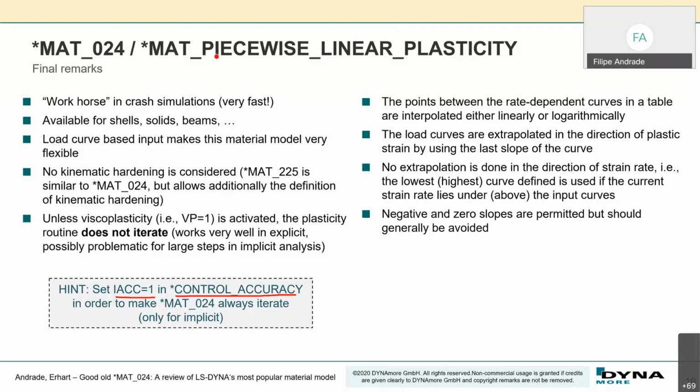Well, the other things we already talked about: interpolation between the strain rate dependent curves, either linearly or logarithmically. Some people ask me what is the best choice. Well, I don't know. It's up to you. Some people prefer this or that.